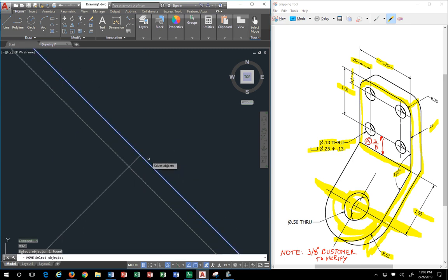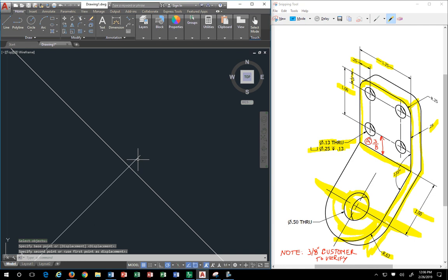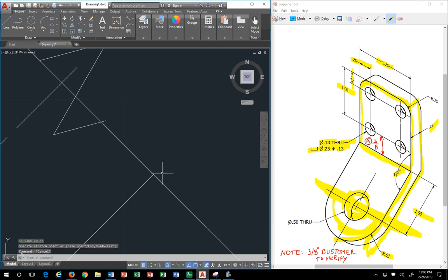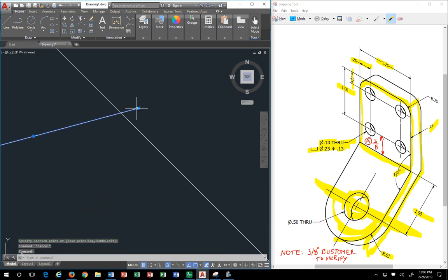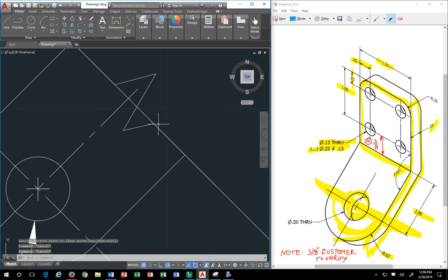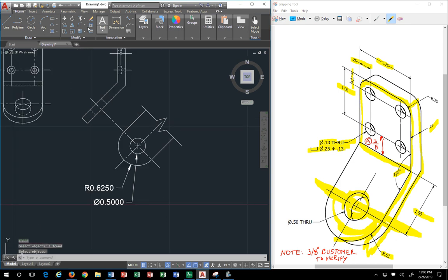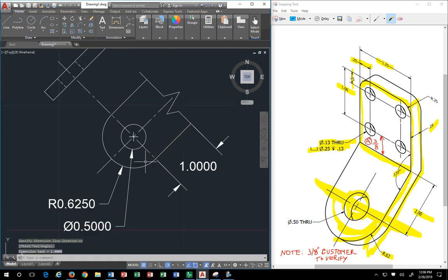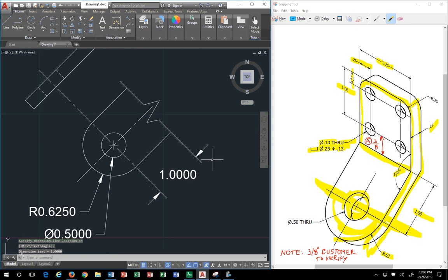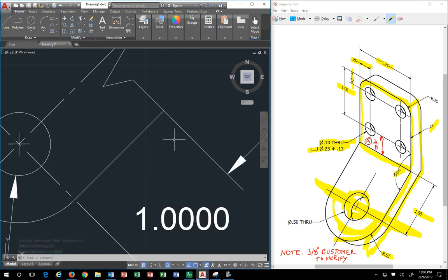So let me move it one more time, this time with a very precise motion. And shorten that up correctly. And of course I'm going to have to shorten this up. Then I could delete that. Okay, now I can drop in a dimension right there, and I'll get that 1 inch mark, the correct 1 inch mark. See that? My break line is too long, so I want to shorten that, because I do want to see the gap